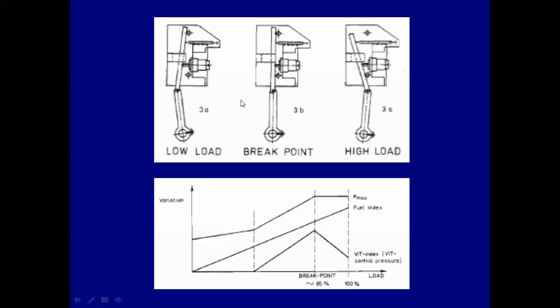But as this arm moves this way from your governor, it's going to increasingly depress that button and change the air signal out. But once it hits that pin, as it keeps moving, then the pin causes the arm to shift the other direction, which then changes your outlet air pressure.